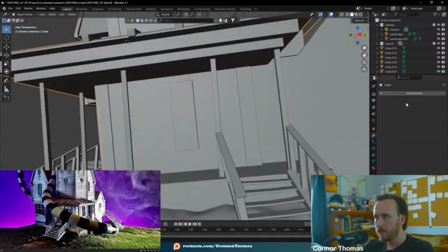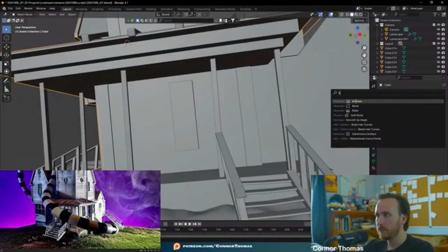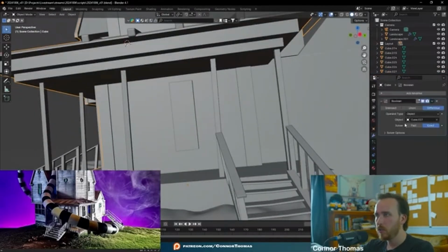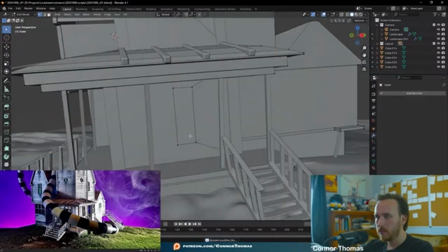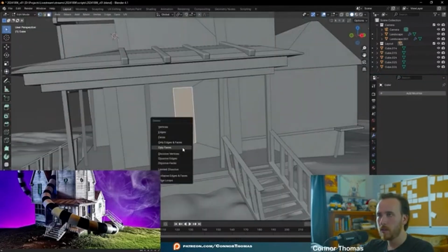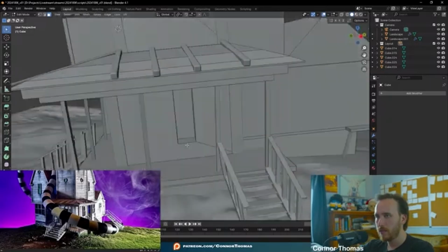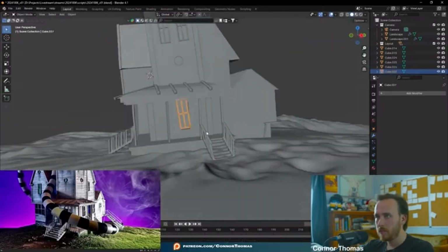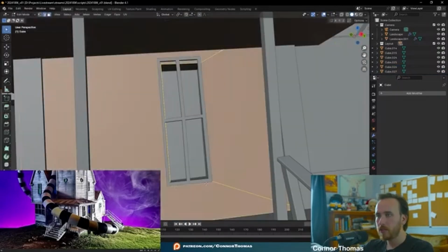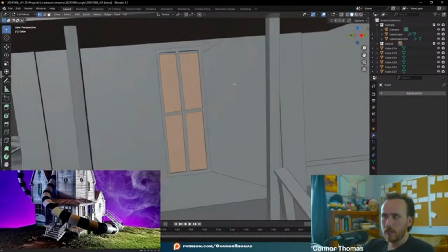That's all lined up. Select this guy. We're just going to add in a nice little boolean. Select our cube, apply that. Now I could just delete that. Now we've got this face, delete only the faces. And it creates ourselves an inlet. I'm going to just duplicate this downwards here, just line this up roughly. Now if we go ahead and just select the outer vertices of this guy, hit fill, and then let's just go ahead and make this its own object again.